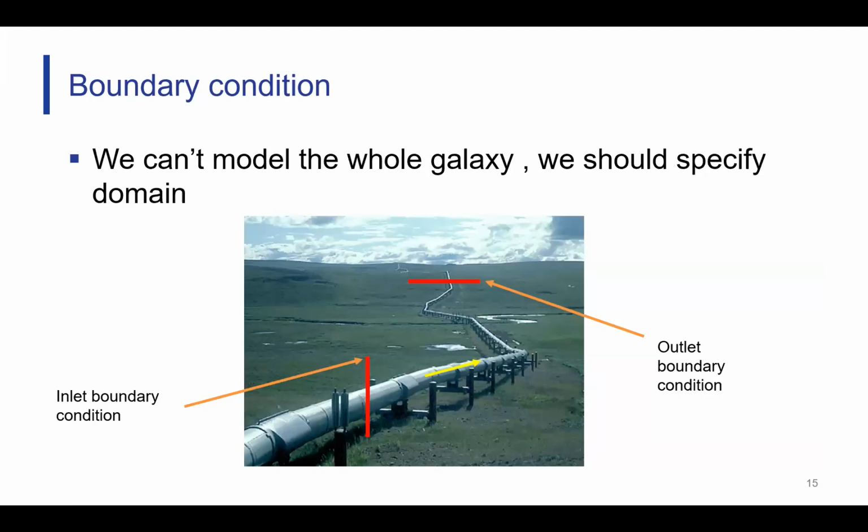Next, we need to define our boundary conditions. We've basically at this stage imported our beautiful geometry into the program, and we need to formulate the conditions. So this is that modeling stage, remember, where we describe the environment to the program. We need to think about boundary conditions. As you recall, we're not modeling the entire world. We're selecting a region of interest, and that's going to be our computational domain. Computational domain, fancy way of saying that's what we're solving.